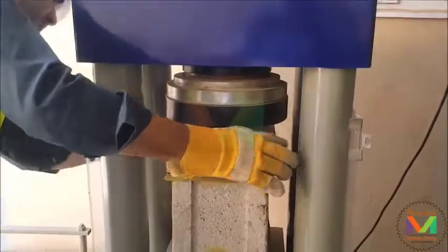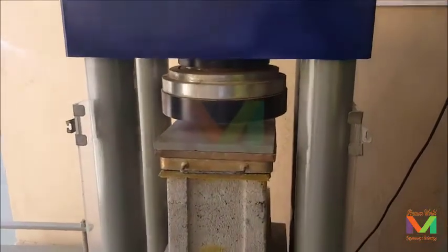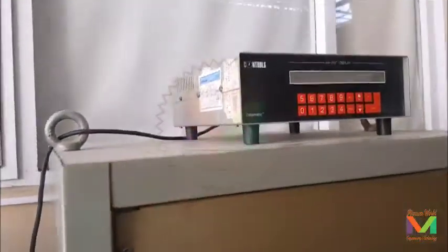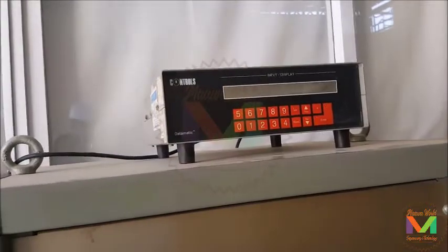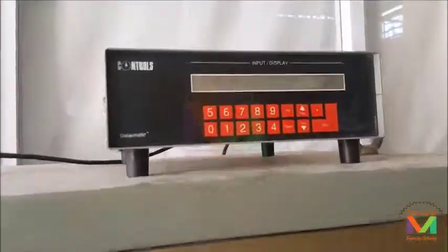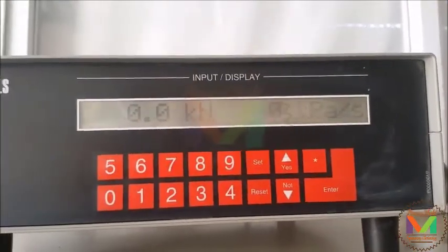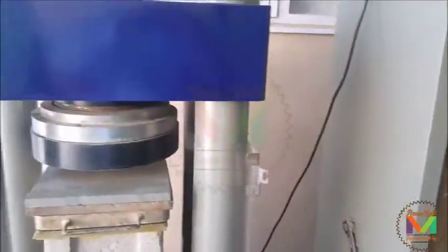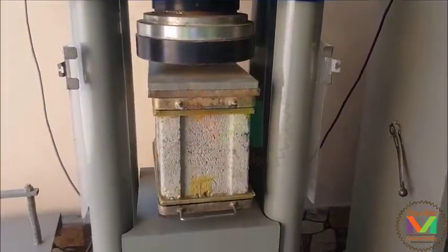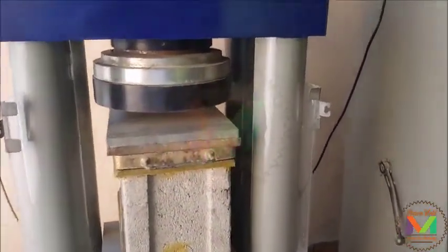As per section 7.1, test apparatus: the testing machine shall have an accuracy of plus or minus 1.0% over the anticipated load range. The upper plate shall be a spherically seated hardened metal block firmly attached at the center of the upper head of the machine. The center of the sphere shall lie at the center of the surface held in its spherical seat, but the block shall be free to turn in any direction, and its perimeter shall have at least 1/4 in. or 6.3 mm clearance from the head to accommodate specimens whose bearing surfaces are not parallel.